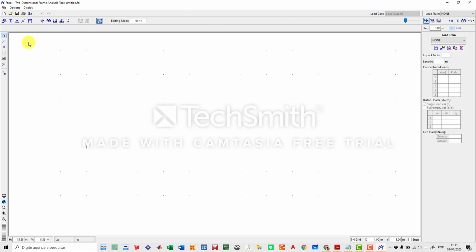Each Ftool command window creates only one structure, but you can create multiple structures in the same grid area. On the right part here, on the bottom, you can create the grid line. The grid line is going to place dots at specific lengths. I don't know if you can see very well from my command window, but the dots are spaced 1 meter apart from each other. If you click on the snap option, such as in AutoCAD, whenever you are clicking to create a frame or a bar, the mouse is actually going to be attracted to each grid point.